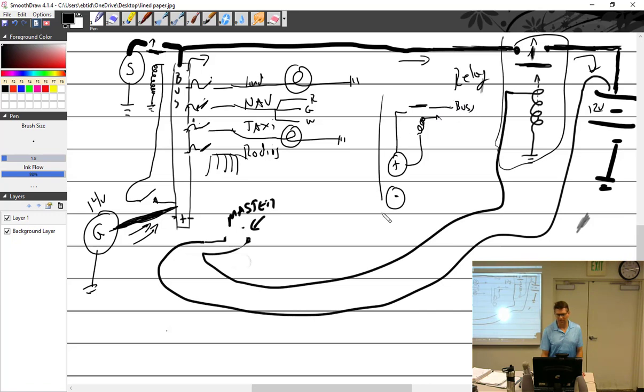I'm just drawing it here because I ran out of room. So when you plug in the ground power, it automatically activates a relay that closes and energizes the bus bar all on its own. So once that's plugged in, that aircraft's live. You don't go in and hit the master switch. Without hitting the master switch on Cessnas, that's the way it is.